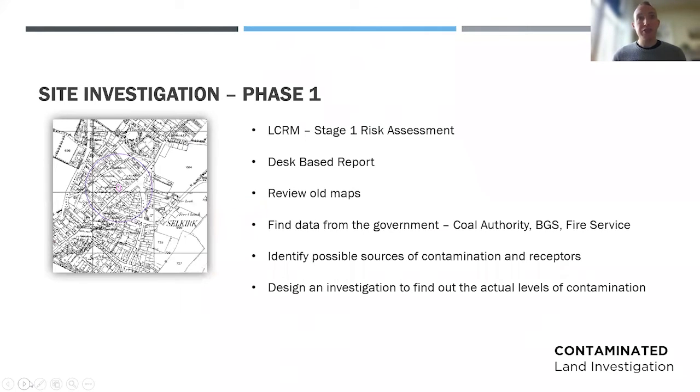The first stage is a phase 1 investigation, also called a desk study. If any of you are starting out in a career in contaminated land, this sort of report is likely to be your bread and butter. It's the preliminary stage of the risk assessment, which develops a theoretical model of the contamination at the site. It's a report produced using existing information. Most people will visit a site to produce this report, but it isn't a necessity.